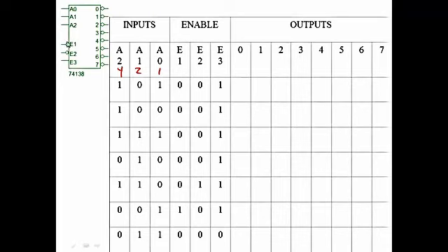These are enable lines, and basically what we have to do with enable is we have to meet these criteria. We have to have a low going here, a low here since they're bubbles, and a high here. So we need a 0, 0, and a 1 for that thing to be enabled. If it's not enabled, we put no output. In other words, they're all highs on the output. We have active low outputs, so whatever number we're putting in, we're actually going to put that out as a low. So let's look at the first example just so we can make sure we're seeing it okay.